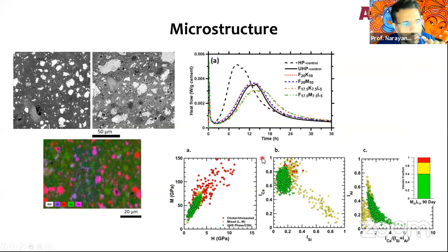So I'm just jumping on to one extra idea. And what does all of this give me? An extremely dense microstructure. So after hydration for about 28 days, now your structure is looking like this. And anybody who has seen an electron micrograph will know that the extremely bright particles that you see are the unhydrated cement particles. So an immediate question is that, well, I bought the most expensive component that I use in concrete, and you're using none of that. See that? My cement is not being hydrated. I'm just leaving it unhydrated.